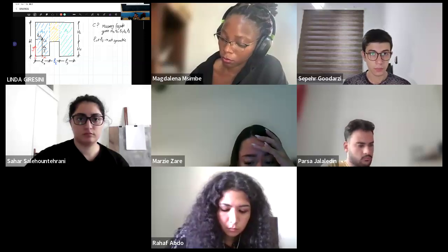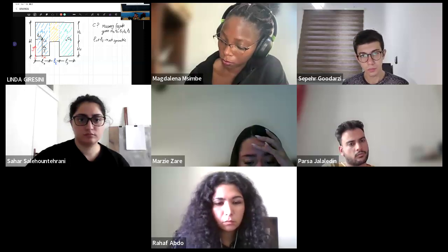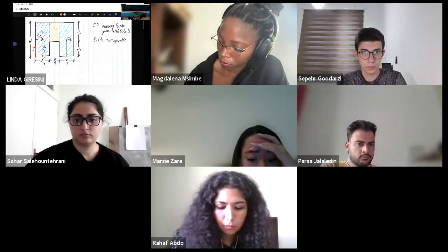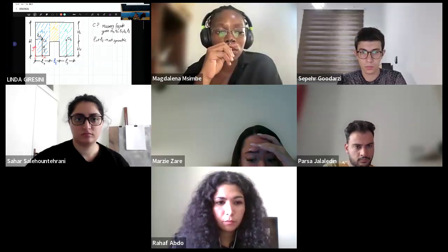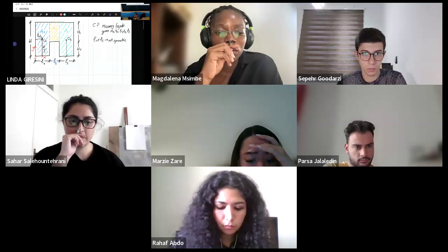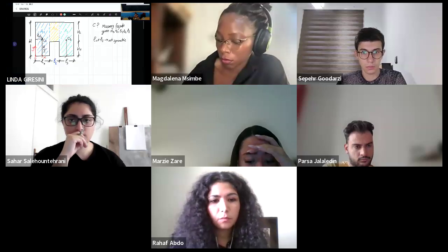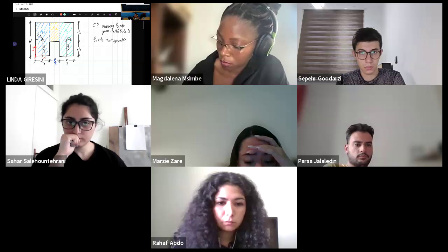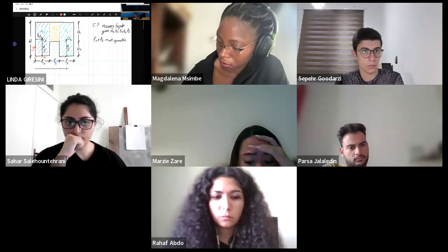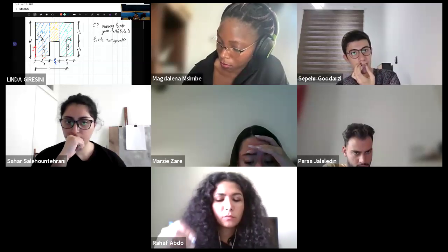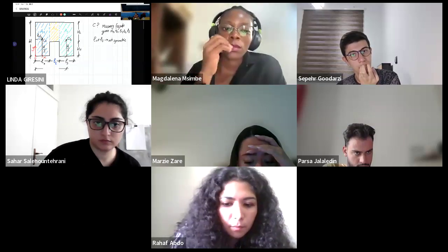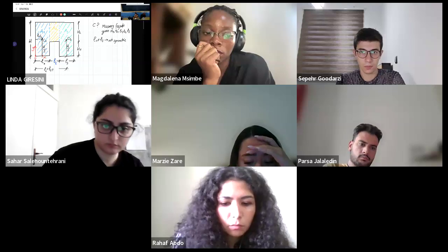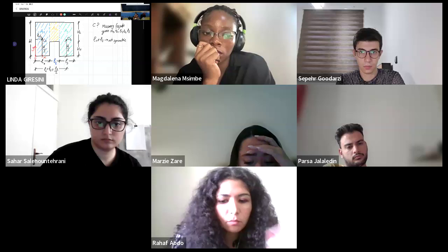Also, I know the distance from C3 because, yes, there is a mistake in here, and you didn't tell me, it is h divided by 2, not h1, because h1 is just the height of the opening, okay? So this is h divided by 2 again for area number 3. And what is the distance of C3 with respect to the y-axis? Let's see. It's L1 plus, yes, very good. This is the distance.